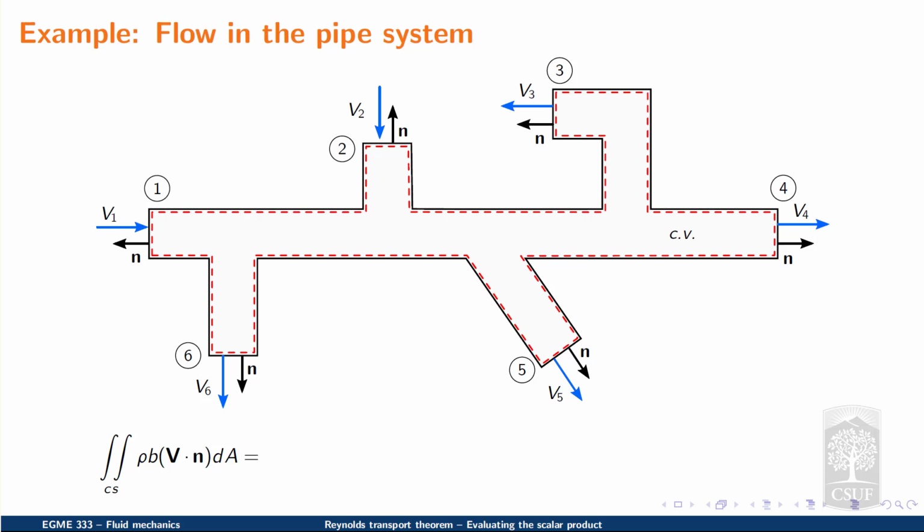The orientation of the unit vector, bold little n, is independent of the local velocity vector. It is simply dependent on the shape of the control volume. But at each of these 6 points of interest, we want to sketch the local unit vector. So if we go through point by point, we can then specify what are considered inlets and what are considered outlets so that we can expand out the one-dimensional inlets and outlets assumption.